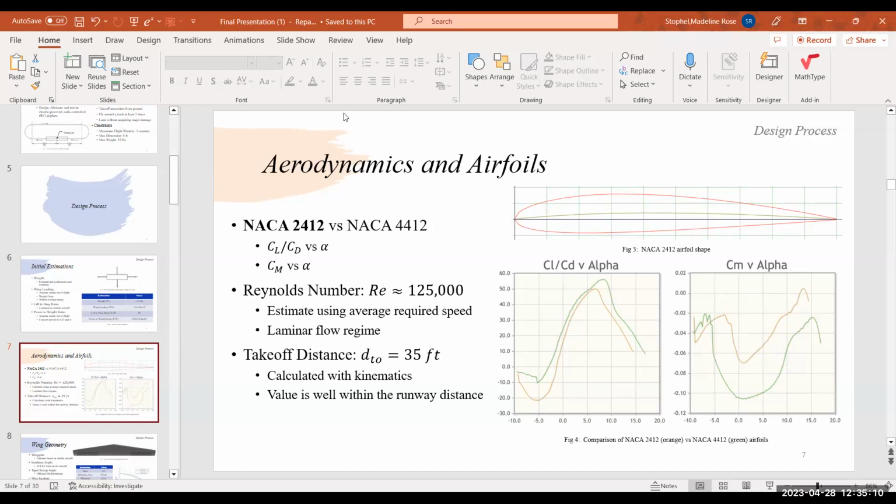Because theoretically, if you use the 4412 and use a longer wing, you get a higher Reynolds number. You'd be in a region of higher stability. So you'd get those oscillations, not that you would really care about it since you're using a positive alpha anyway. But those initial oscillations between -10 and -5, I predict will be gone for the CM.